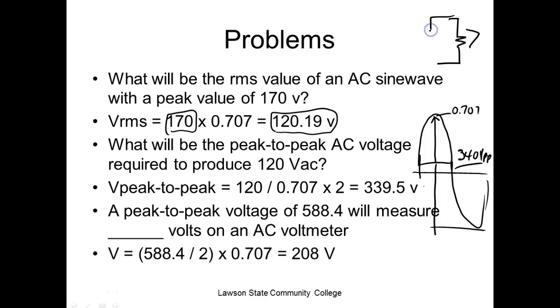What we're doing is we're talking about the source. What goes on with the source, right? Y'all understand? Not the load, the source. So that means if I've got this 120 volts right there, and this is producing so much power, like we said, 1,000 watts, and then I move it over here, then I have that 1,000 watts over here, but this is going to be at a different voltage, which means the current is going to go down, but it's still delivering 1,000 watts to the load at a voltage that's required by the load.